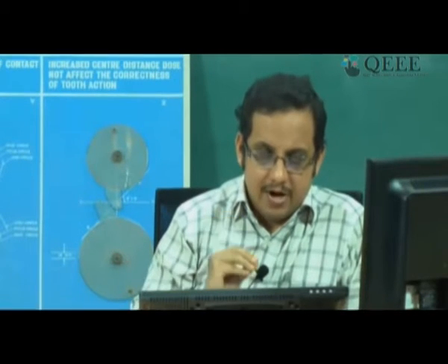So, as I said, this mechanism of gearing does not work on the principle of friction, right. It is perfectly permissible to have sliding between the two surfaces, which is why it is a higher pair mechanism. In a higher pair mechanism, you do have sliding as well as rolling without slipping. It is only in a friction disk that we take the approach that there is no slipping possible at the point of contact. But in the case of a gear tooth engagement, if the point of contact is anywhere other than the pitch point, then there is relative slipping between the two gear tooth profiles. I hope I have answered that question.